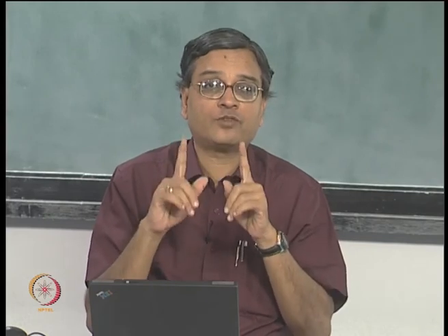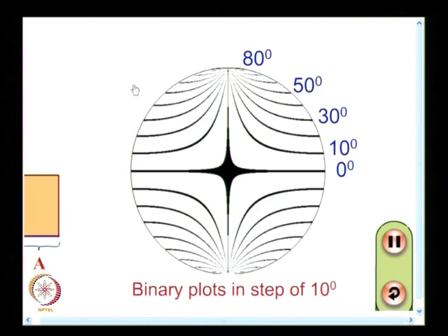And what I find here is that I have sigma 1 minus sigma 2 contours superimposed over the isoclinic contours, and I do not see all the isoclinics in one shot. I have to scan the image and pick out this information, and get it as a separate image of isoclinics. So, without getting into the experimental details, I have tried to project what is in store for you. In some experimental techniques, you get the information separately.